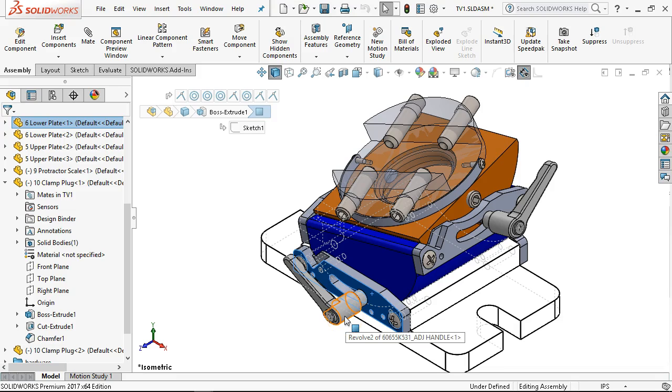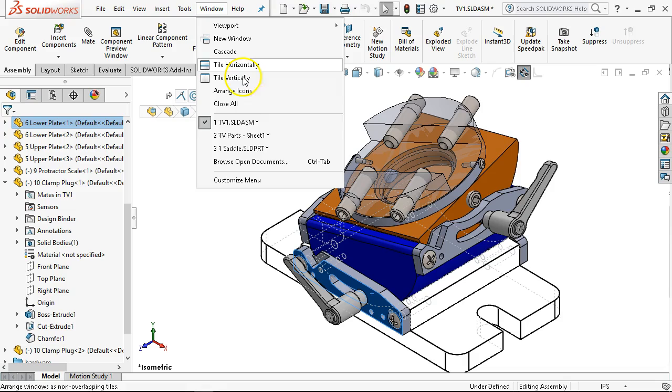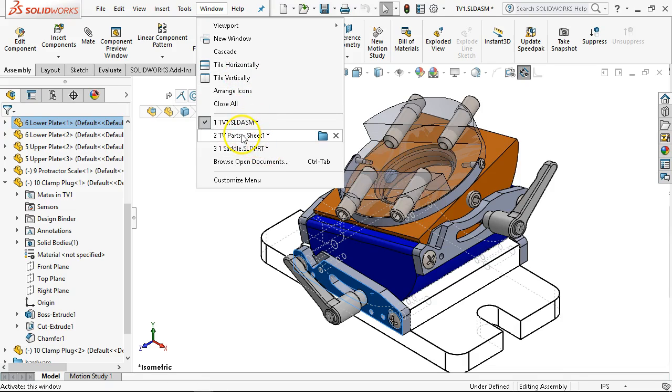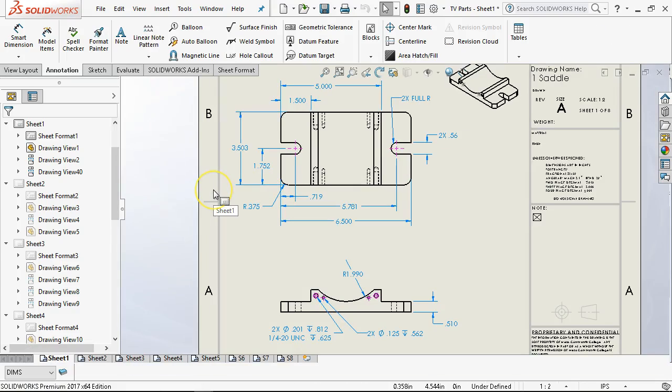It just needs to be flat and perpendicular. So an inspection may be okay, but the tolerance isn't. Well, I say that, and then how tight is the tolerance? So it was plus or minus 1.5 thou. If the surface roughness is not an issue, then I would think that we could hold plus or minus 1.5 thou, 2 thousandths without that much issue.